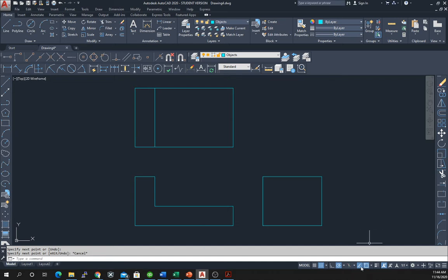So you need to make sure you have object snap on, and then you need to make sure you have snap cursor to 2D reference points on. So you should see this on, you should see this on. Here, you can be at 90, 180, 270, 360. In fact, let's move this to 30, 60, 90. This will make it a little bit easier, and you'll see why in a few minutes. And then here you should be on polar snap, not on grid snap.